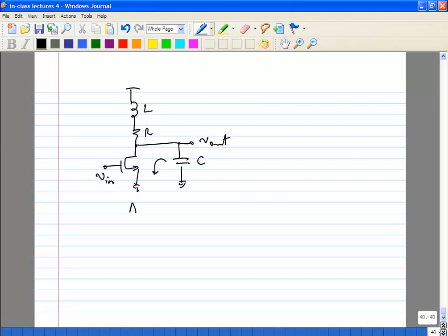So what is your gain now? It is nothing but Gm times Z(s), where Z(s) is the impedance. Let's assume Gm is constant because we know the trade-offs involved in changing the current and size.